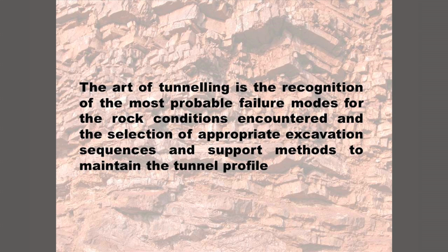A definition of the art of tunneling might be this: it is the recognition of the most probable failure modes for the rock conditions encountered and the selection of appropriate excavation sequences and support methods to maintain the tunnel profile. The tunnel profile is fixed by the function of the tunnel, so that if you have a highway tunnel for 2 lanes of traffic, it has to have certain dimensions, certain height, in order to accommodate the lane width, the services, the ventilation, the drainage, and so on. Or an underground powerhouse has to have certain dimensions in order to accommodate the machinery that goes into it.